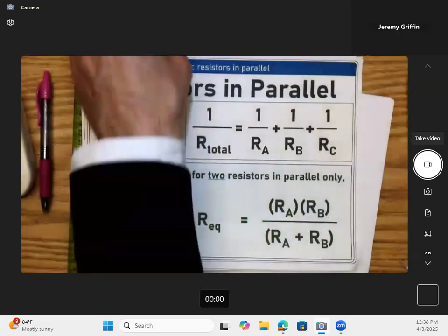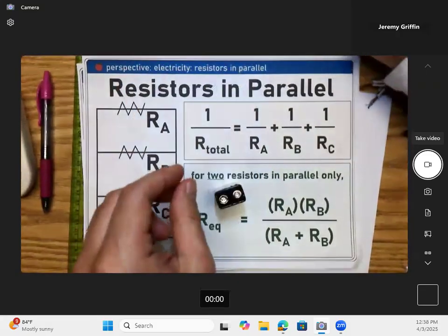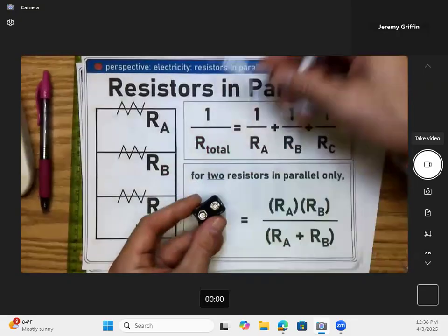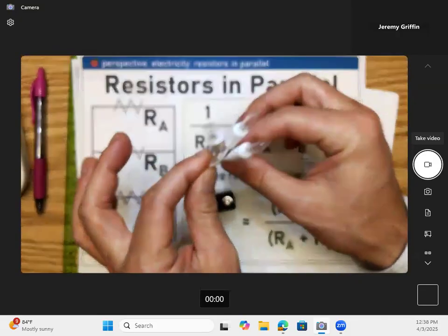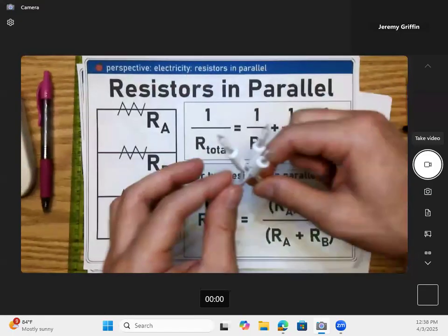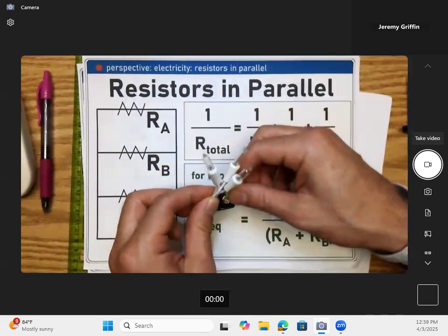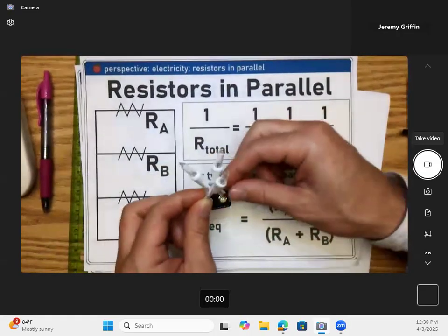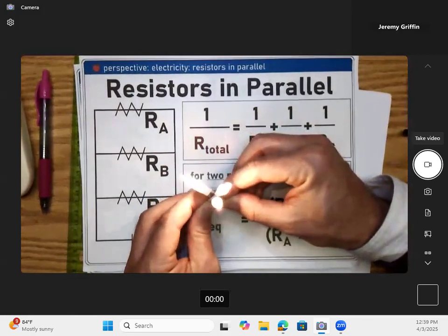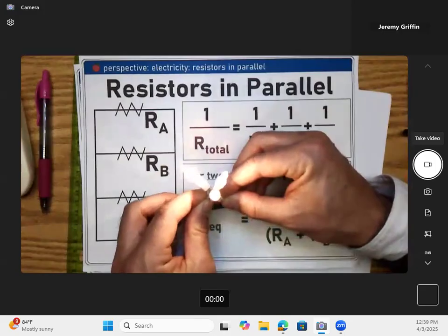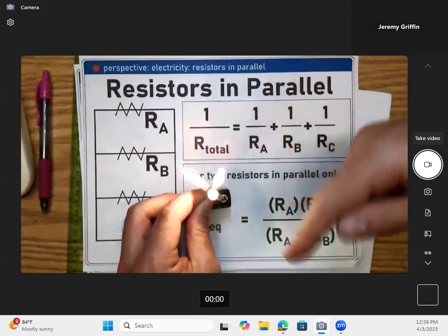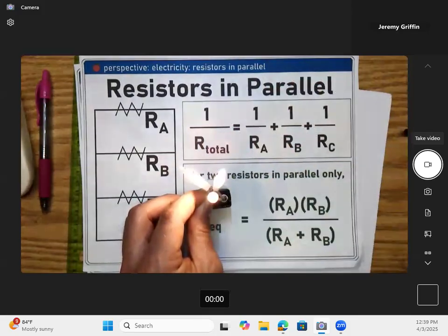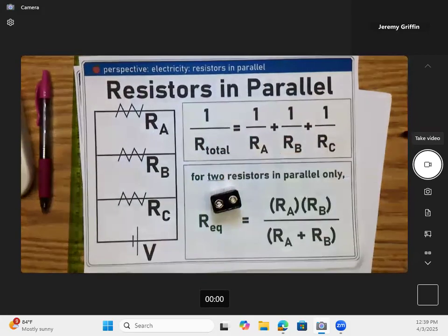Right. And finally, let's do the physical model. So 9 volts, 1 ohm resistance. You guys see, okay, so that's pretty bright for a single bulb. All right. But what if I have 3 in parallel? Ooh. Well, if a single bulb was like 1 ohm, I bet this would overall be like a third of an ohm. Right. But let's see what happens in terms of current. Well, guys, is every single one of these bulbs about to have the full 9 volts going across it? Yeah, what's that going to look like? Pow! Now, every single one of these is really bright. Right? Okay. So now compared to 1 bulb, this battery is supplying 3 times the current it was to 1 bulb because it's 9 volts across this one, 9 across this one, 9 across this one. So every one of these is getting some current. Right, there you go. Parallel.